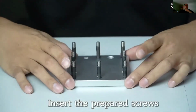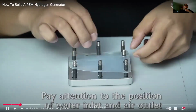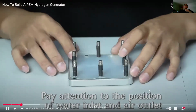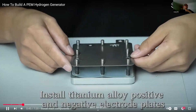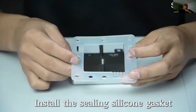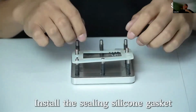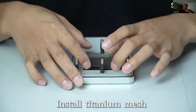And reverse. Install the insulated gasket. Pay attention to the position of water inlet and air outlet. Install titanium alloy positive and negative electrode plate. Install the sealant silicone gasket. Install titanium mesh.